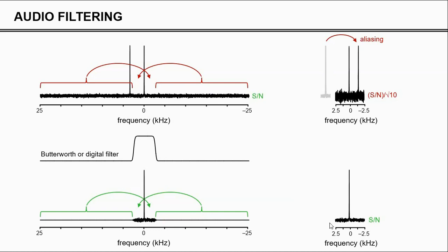So this could be a problem. If you expect a spectrum with 2 signals in it and you only observe 1, you might be very much confused, or it may even lead to an incorrect conclusion. One thing to notice also is that these filters are not applied in the frequency domain. They are typically applied in the time domain, but the effect is as shown here for the frequency domain.